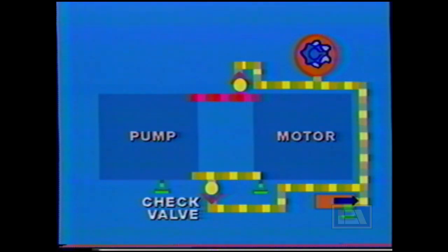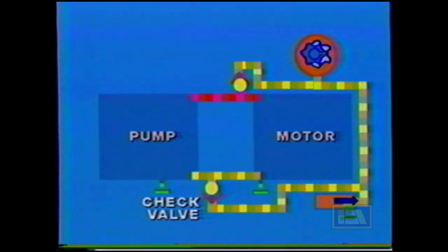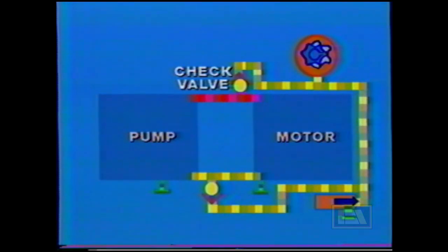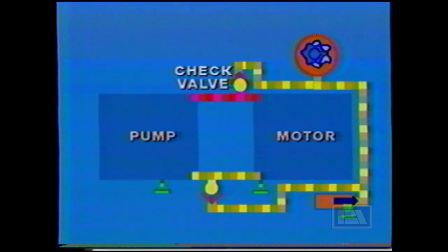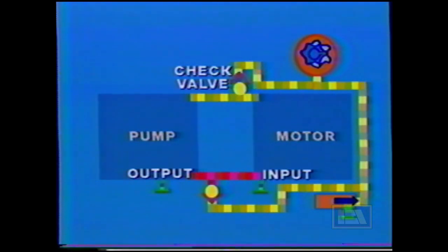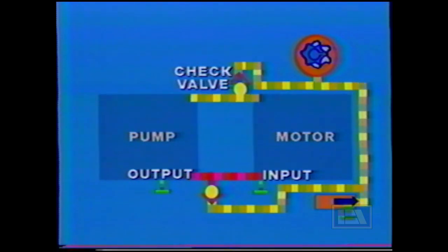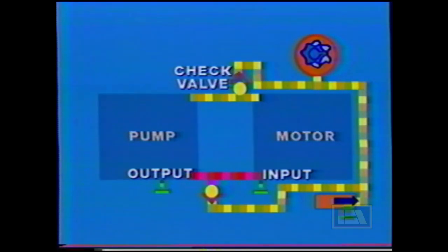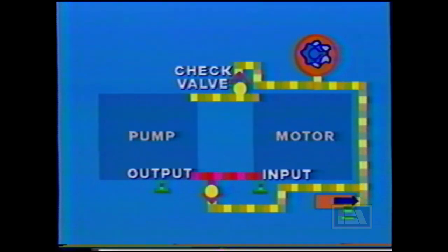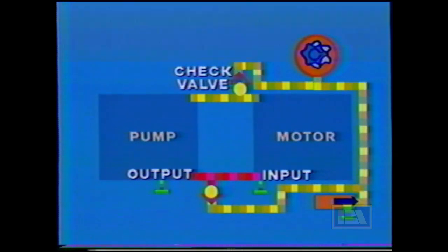However, the charge system must also be able to compensate for this change. To do this, the system uses the other check valve mounted on the opposite side of the hydrostatic loop. Now, when the pump reverses its direction of flow, the high pressure side or outlet side of the pump seats the check ball on that side of the loop. The low pressure side check ball is allowed to open, and once again, charge pressure oil can enter the loop.